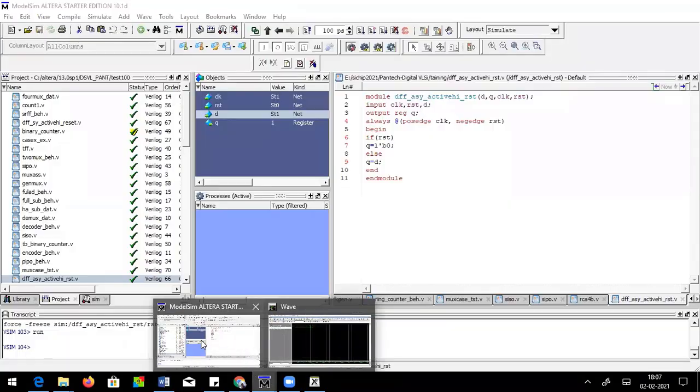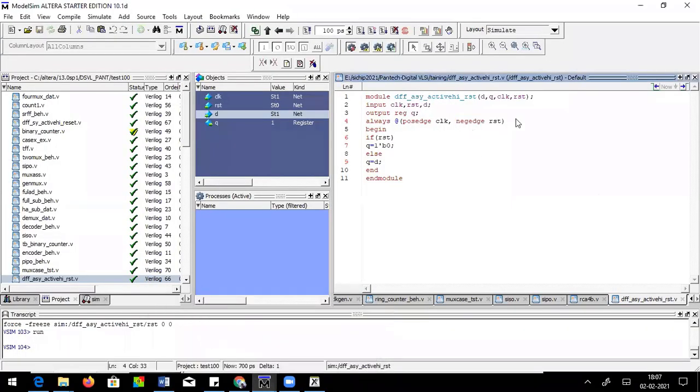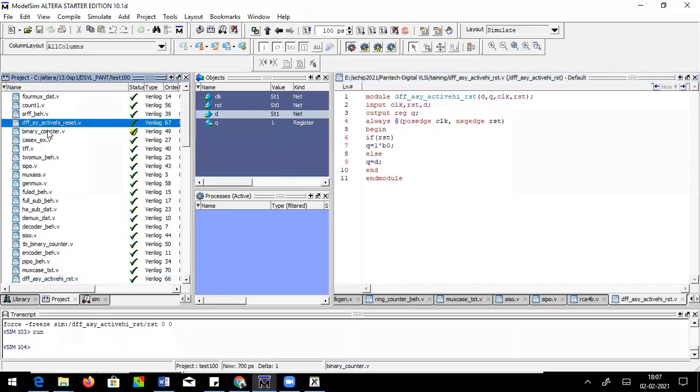Very similarly, you can even make this posedge of the clock, posedge of the reset also. So you can try with all possible options. But in order to avoid confusion, it's always better to have synchronous, active low reset. That will be much more sufficient. Unless you have some very specific need, you need not use all these possible combinations, because very frequently the thing being used is D flip-flop with synchronous reset.